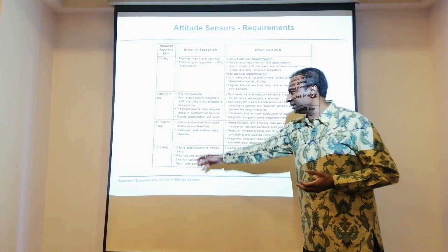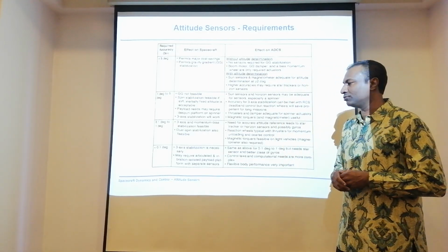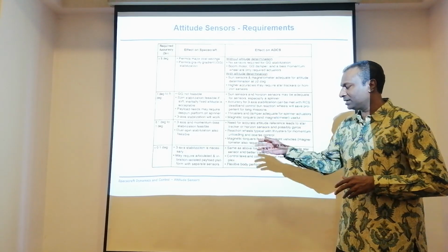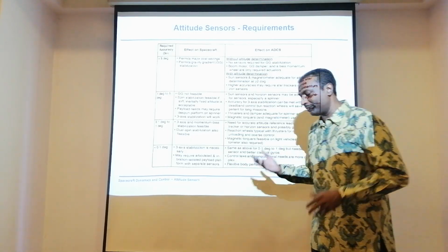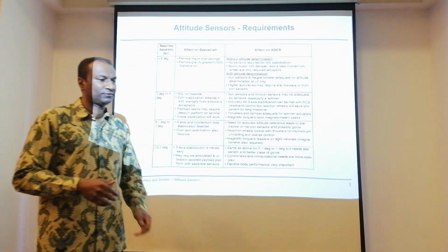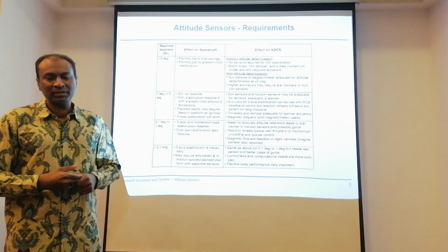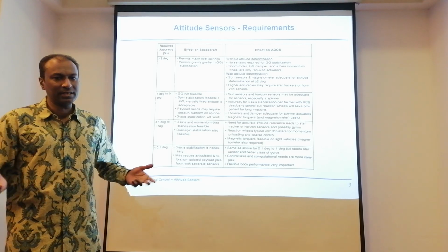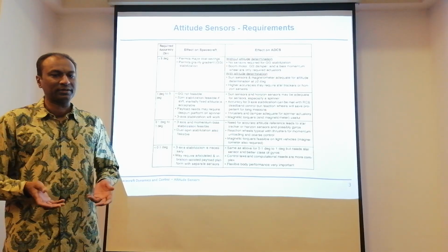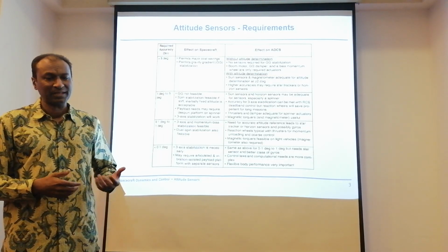Now, for the most typical or rather good quality satellites, we must have good quality measurements. Assume that it's 0.1 degree or better. It could be even 0.001 degrees of attitude accuracy. Then we are looking at options like the gyroscope. That is mandatory. If you have those classes of sensors, obviously you will have good, solid actuators as well.